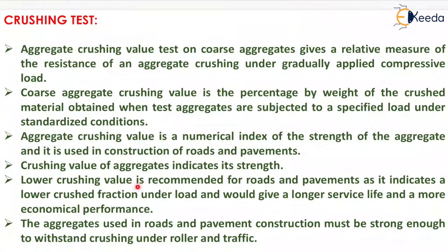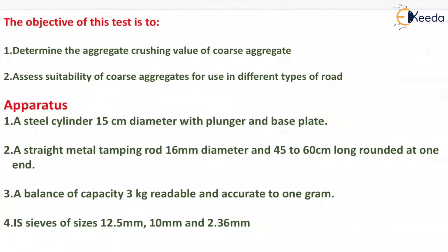A lower crushing value is recommended for roads and pavements as it indicates a lower crushed fraction under load and would give a longer service life and a more economical performance. The aggregates used in roads and pavement construction must be strong enough to withstand crushing under roller and traffic. The objective of this test is to determine the aggregate crushing value of coarse aggregate as well as assess suitability of coarse aggregate for use in different types of roads.